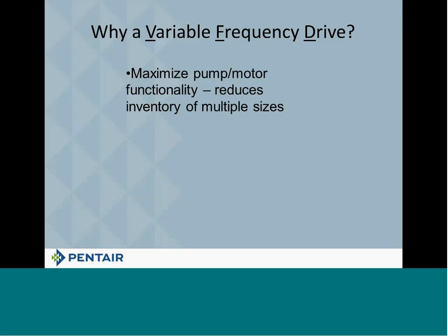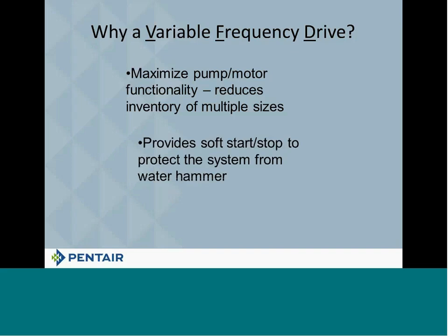Okay? Now, of course, you've got to check and make sure that that's going to work with every pump, because there is a minimum continuous stable flow on pumps. If you go below that minimum continuous stable flow, even if you've got a drive on there, you're going to have a problem. So check your minimum continuous stable flow before you say, oh, I don't need that jockey pump. Okay? And then lastly here, it provides a soft start and stop.